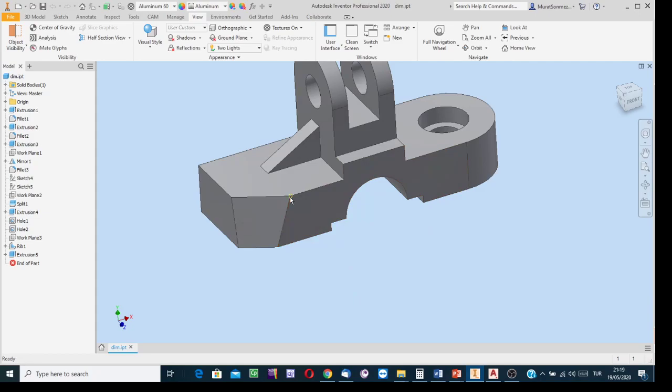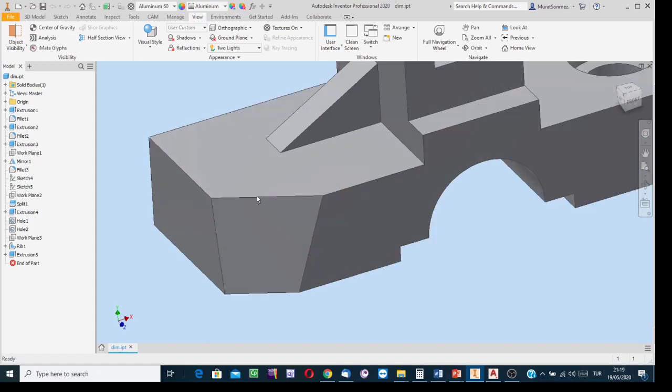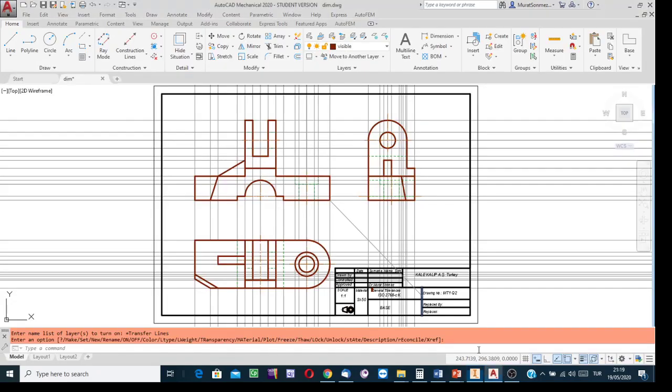For instance, after having the projection of this point, projection of that point, then between them we have this intersection. Start line drawing process if you're drawing the projections line by line, and then indicate this point, indicate that point in AutoCAD. Yes, after having the images of the points, then start the line drawing process and then join the images of the characteristic points with the necessary joining lines.